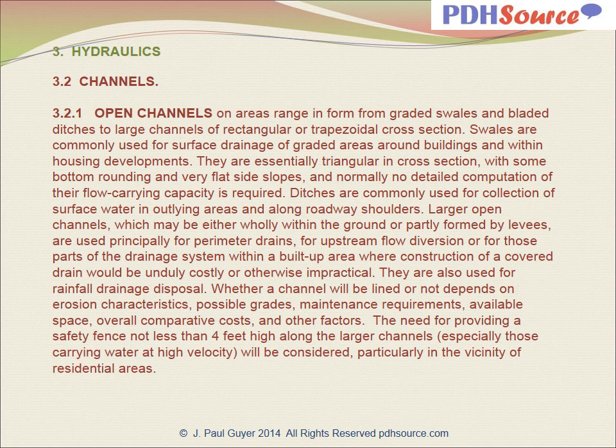Channels: the hydraulics of water flow in channels. Open channels on areas range in form from graded swales and bladed ditches to large channels of rectangular or trapezoidal cross-section. Swales are commonly used for surface drainage of graded areas around buildings and within housing developments. They are essentially triangular in cross-section with some bottom rounding and very flat side slopes, and normally no detailed computation of their flow carrying capacity is required.